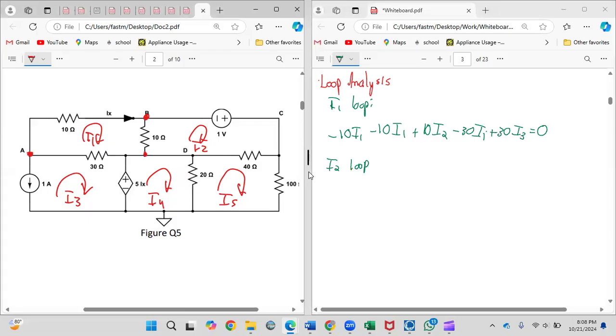If you get the voltage source, you get through. Remember, in loop analysis, you want the voltage drop across the components. The reason why the super loop exists is because you don't know what the voltage drop across the current sources is.